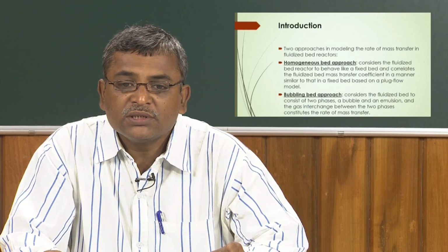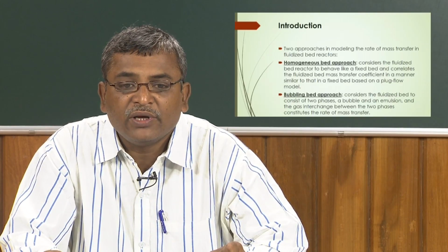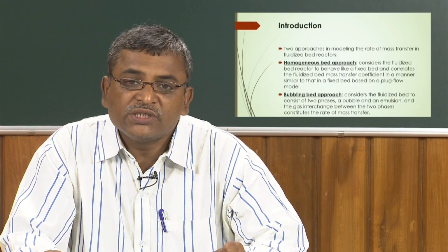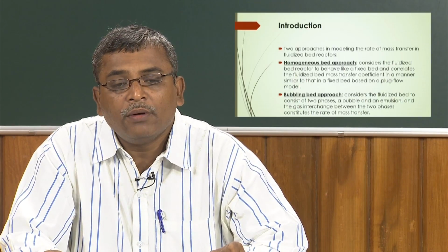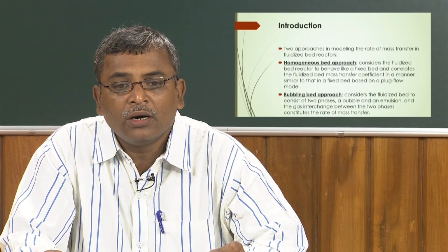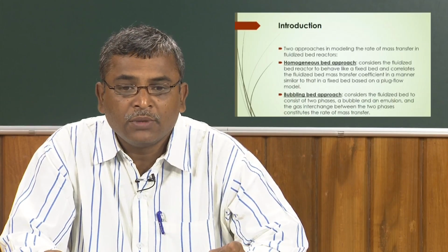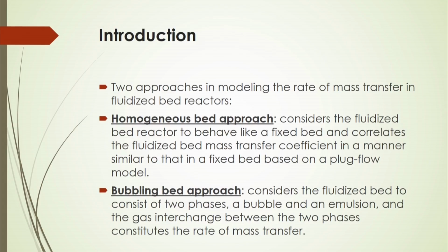So, two phases, a bubble and an emulsion phase, and also you will see there will be an exchange of gas between these two phases, that also constitutes the rate of mass transfer inside the bed.